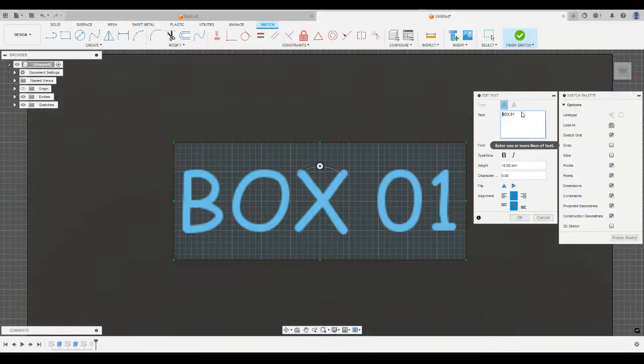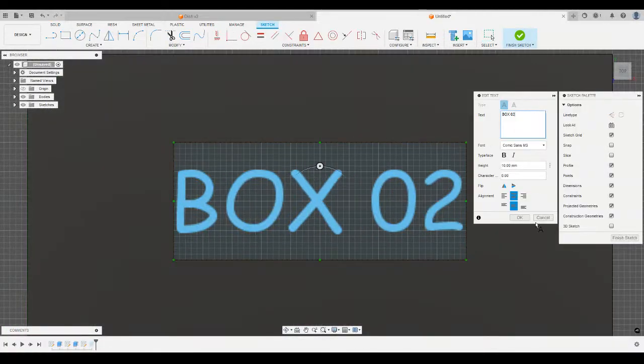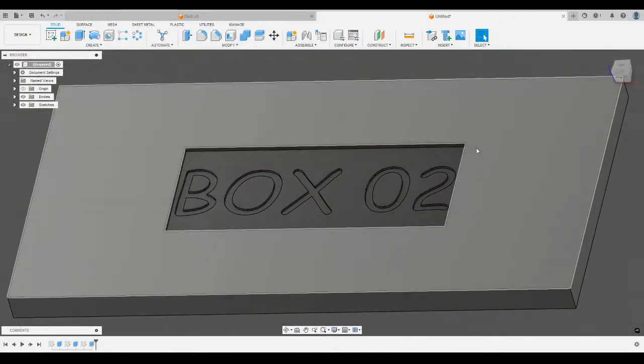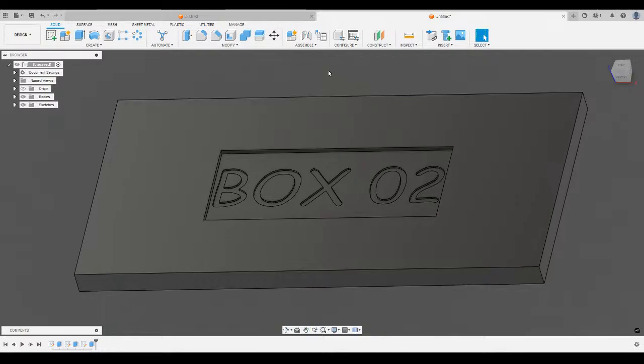Can I revise that? So this is now going to be box number 2. 2 layers because we're normally printing at 0.2 millimeter. Wow. Yeah, 0.2 layer height. So 0.4 would be 2 layers. This is insane. I have been using Fusion for years and years and years. If this isn't new, I look like such a dummy right now. I swear, it doesn't matter if it's new to you. I swear, this is new. This did not used to be a thing you could do.